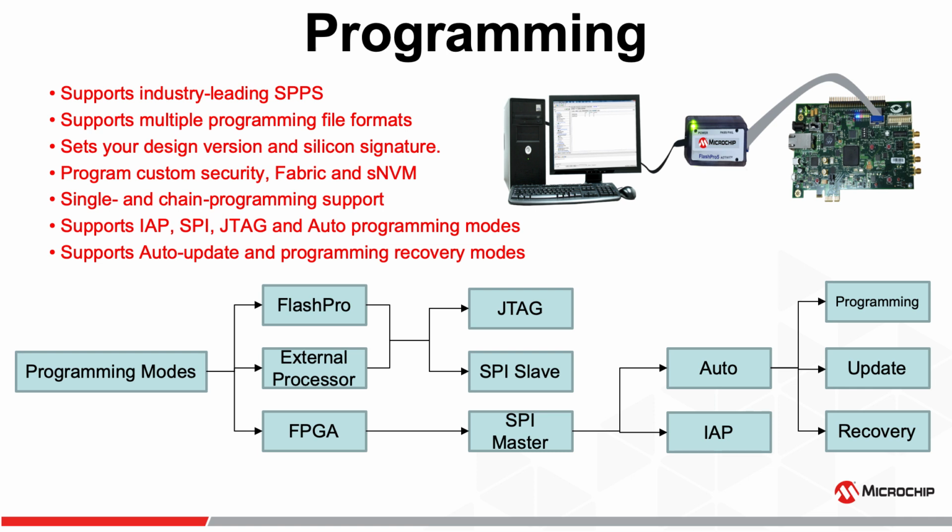Then auto recovery. When you are programming the FPGA, if an interrupt occurs and the FPGA goes to an unknown state, at that time auto recovery will try to program the FPGA with the highest version of the bit file available in the external flash.